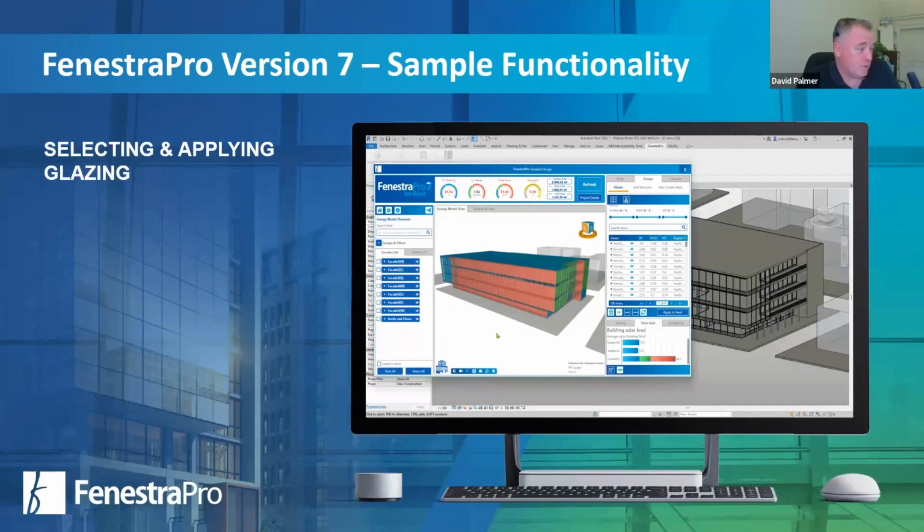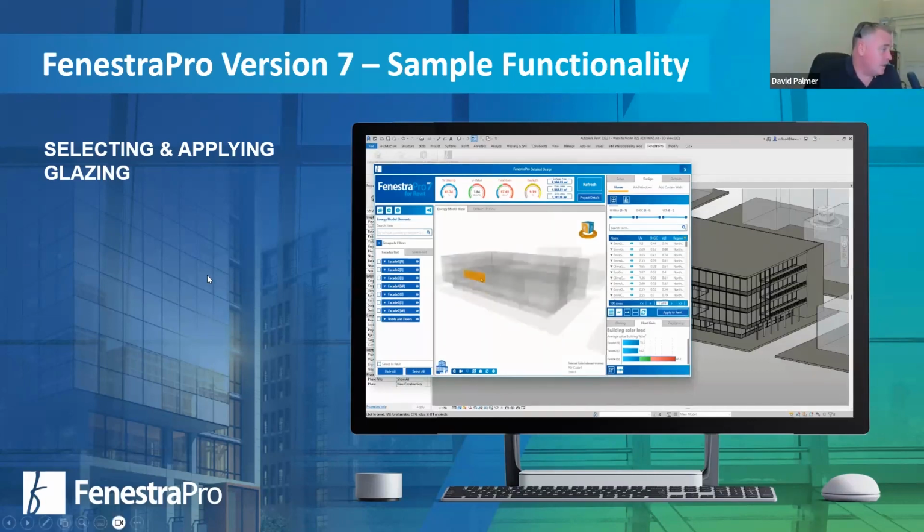Whereas when we get into the actual detail Revit models, which is your more common use of Revit, the data that we're looking to manage and control is actually within the Revit model. So it's a case of how we apply those property settings into the walls, into your roof in terms of U value, your glazing settings in terms of the glass specification, and your heat gain coefficient, U value, VLT, and so on. Let's play on as we start talking about it.